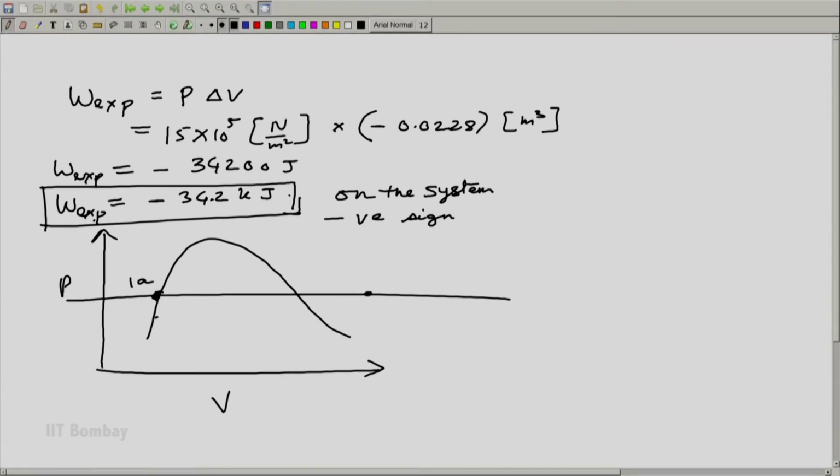So, somewhere around this point, 15 bar 250 degree centigrade, 15 bar saturated liquid, and we also found out that when these two streams came together, this stream came from here, this stream came from here, both of them came and this mixing resulted in a wet steam which has got X as 0.4273. So, somewhere around here was state 2. This is how we can show that because of mixing of 1A and 1B, point 2 came as a state 2 because of this process.